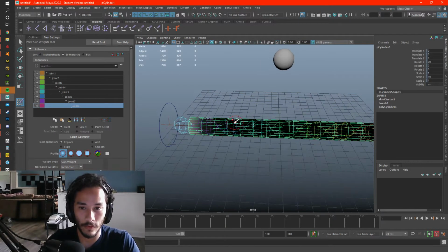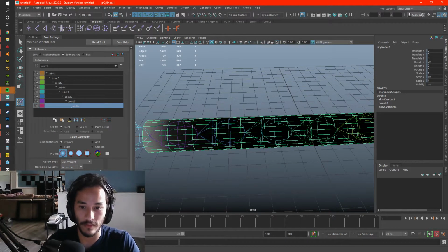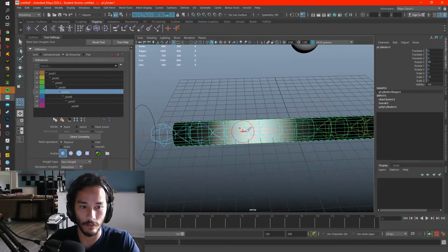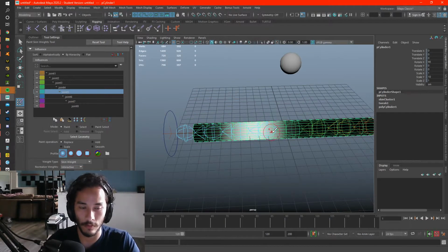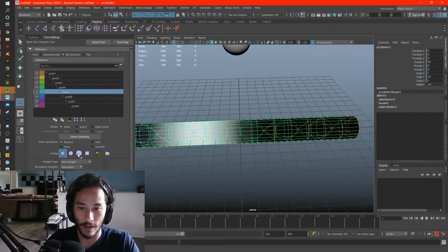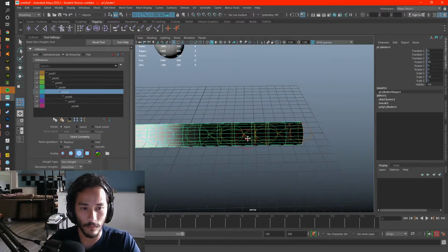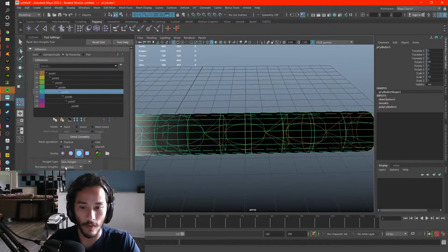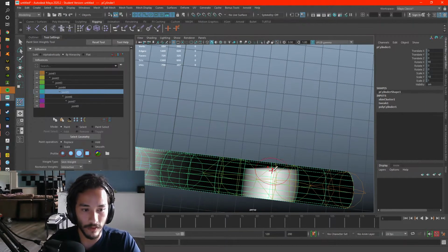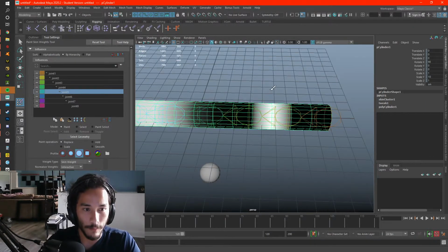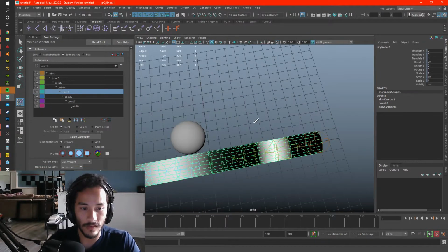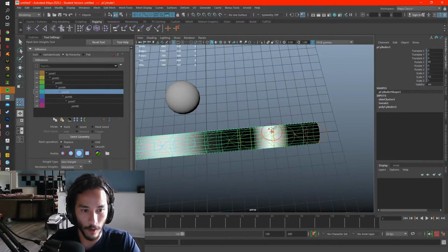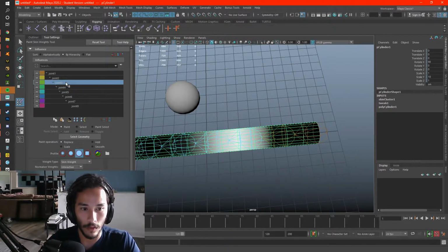What interactive is going to do, if I add weights, let's say I have joint 5 selected, this mesh or this joint, and I add weights to a different section of the mesh, with normalized weight set to interactive, it's going to add weights onto this portion of the mesh, but it's now going to remove weights from whatever this part of the mesh was already bound to.